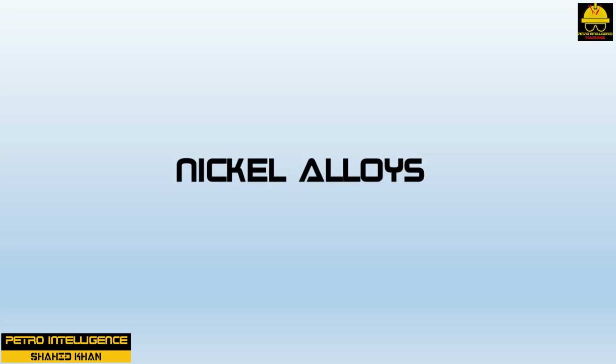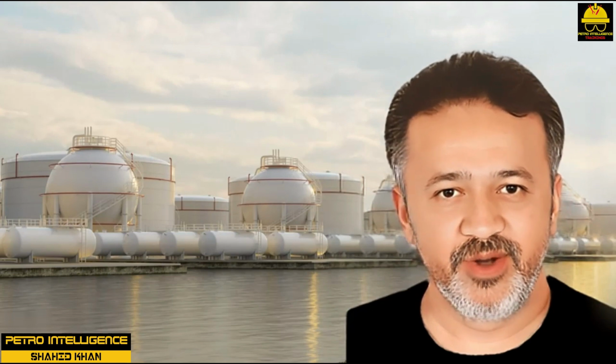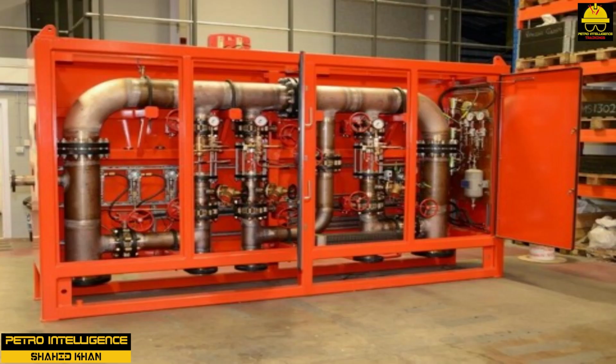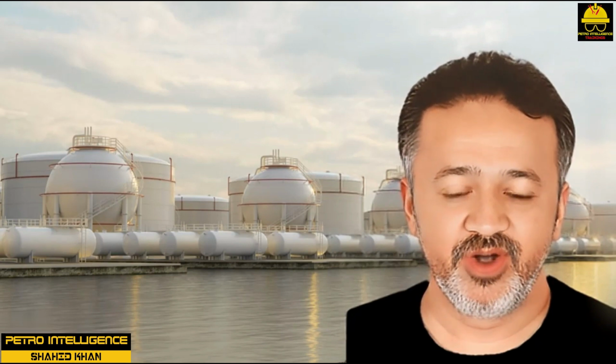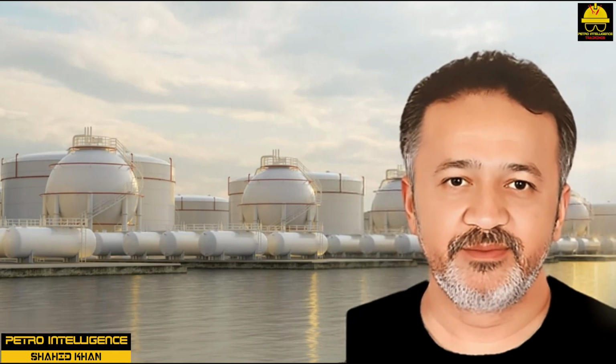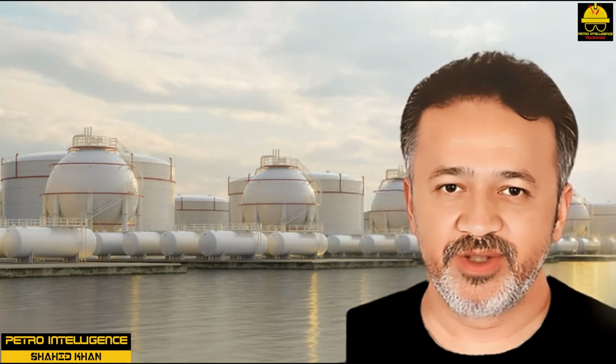Nickel alloys. In a few locations around a chemical plant where extreme resistance to chemicals is required and the stainless steels are unsatisfactory, a group of alloys containing large amounts of nickel are used. These alloys usually contain additions of iron, copper, aluminum, chromium, cobalt, and molybdenum. Some typical examples of these alloys are Monel, Hastelloy, and Inconel. These alloys are used in a variety of services that involve acids and caustics. For example, Monel is used in hot sodium hydroxide or hydrochloric acid service.